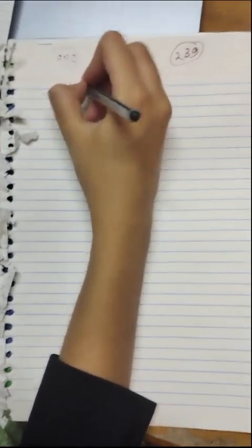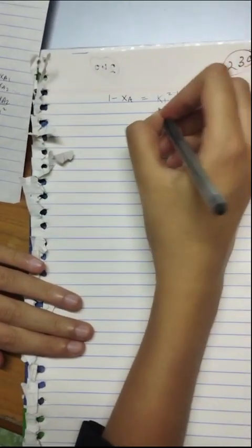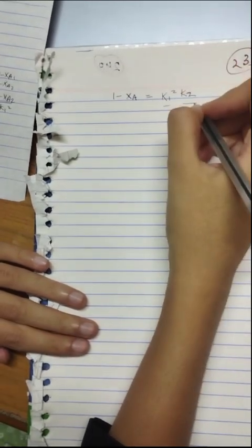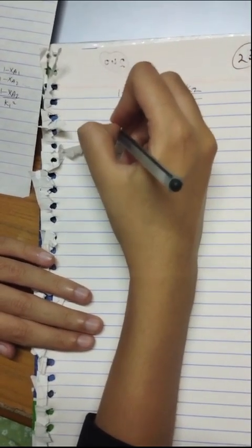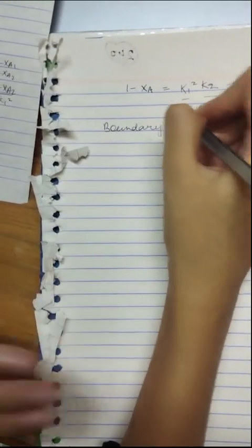So now moving on, we got our equation as 1 minus xa is equal to K1 to the power z into K2. Now to get our constants of integration, which are K1 and K2, we would need to use boundary conditions. So how will we use the boundary conditions? We will refer to the book. In the starting only it was mentioned that the concentration at a surface can be specified, for example X is Xa naught. So we will move on to the diagram here.